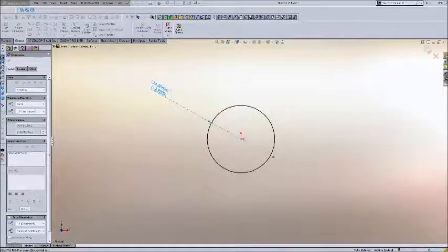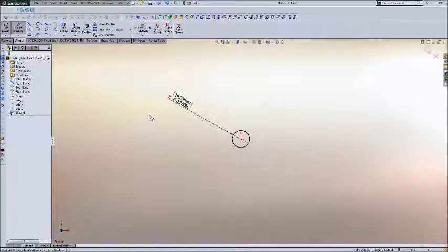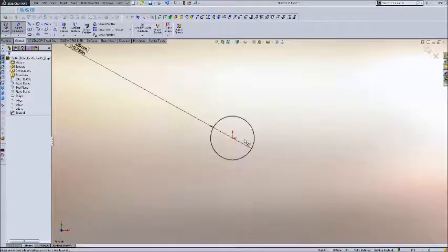There's an equation for the outer diameter of a gear that I'm going to put in the description of this video. What I would normally do, which you can't see, is put the equation into smart dimension. So what I'm actually going to type in is: your outer diameter is equal to your tooth count, so I'm going to say 13 because it's my 13-tooth gear, plus 2, which is a constant. So there's always going to be plus 2. You're going to divide that by the diametrical pitch, and since this is a 20 DP gear, it'll be 20. So 13 plus 2, the quantity of that, which is 15, over 20. And that's going to show as 3/4 of an inch. That's going to be my outer diameter, the outside of my gear.